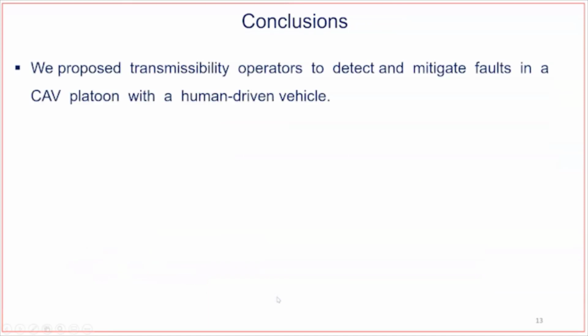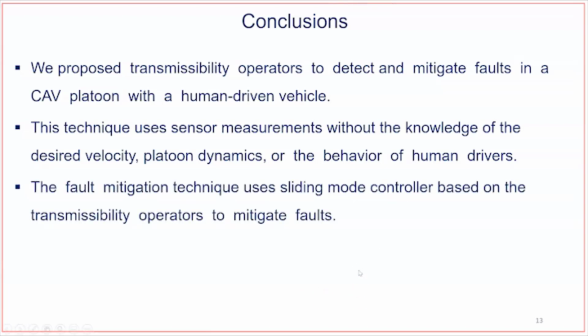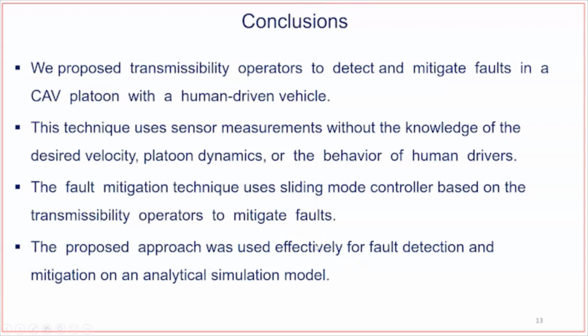To conclude, we proposed transmissibility operators to detect and mitigate faults in a mixed autonomous and human-driven vehicle platoon. Our technique uses only available sensor measurements and is completely independent of the desired velocity of the platoon, the human-driven effect, and the platoon dynamics. The faults were mitigated based on the sliding mode controller that is based on the transmissibility operators. And as we saw, this technique was used successfully in simulations and in experimental results.